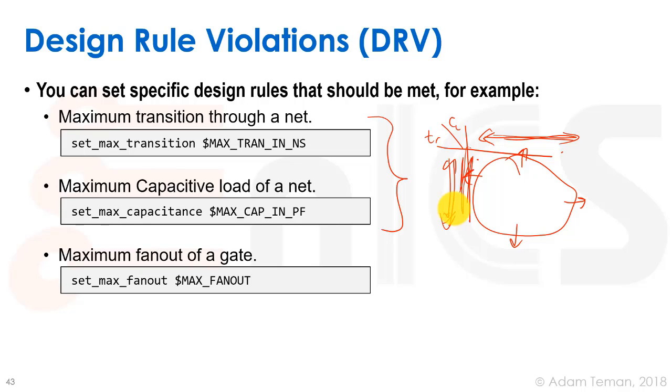You can also define a max fanout of a gate. That just says, okay, we have some inverter, don't let this inverter have more than a fanout of 20. So you'd say set_max_fanout 20 or something like that. It's not usually a straightforward constraint. More like a max capacitance would be the constraint, but as a rule of thumb, we may want to keep such a max fanout.